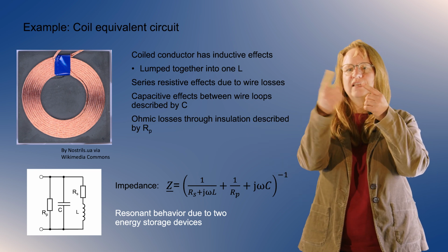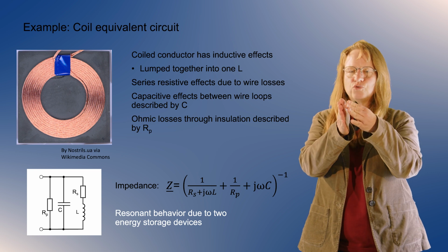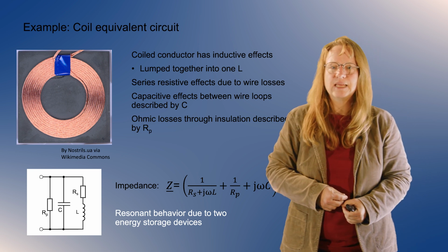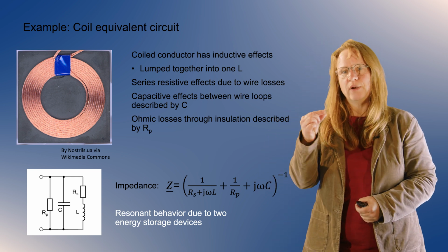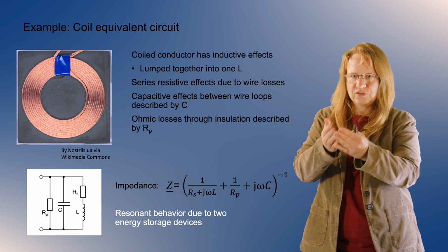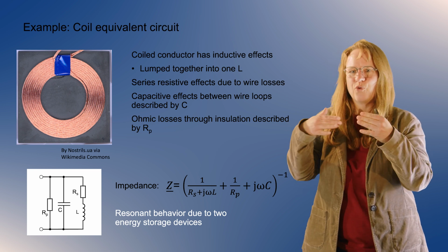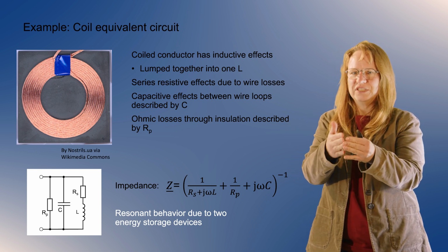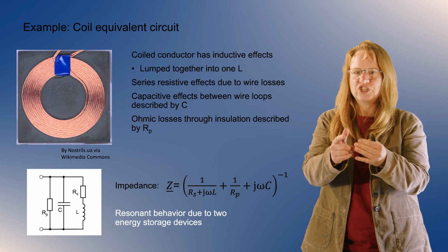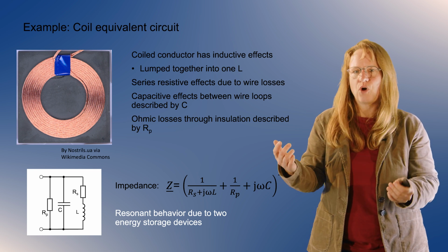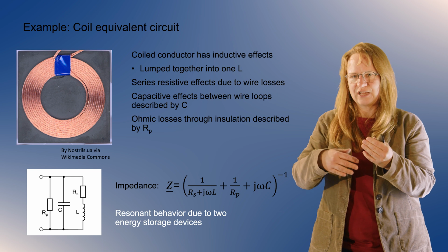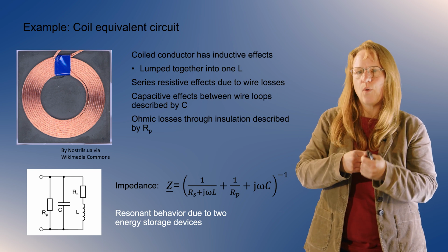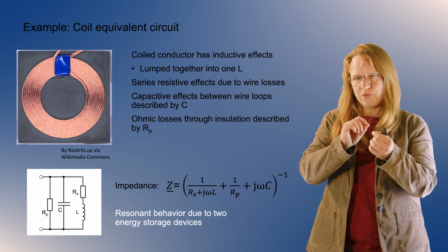If we have several wires running next to each other, they are separated by the insulator between the wires. If it wasn't for the insulator, it would not work out. If you wind a coil, you cannot just take a blank copper wire. It would all be connected electrically, but you need a copper wire that has an insulator around it.